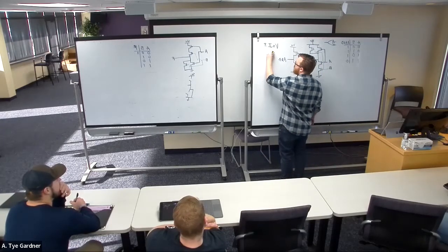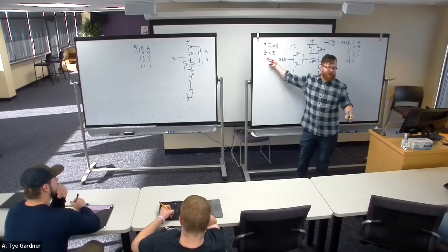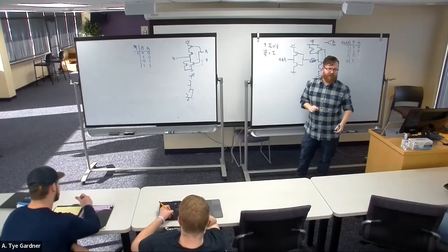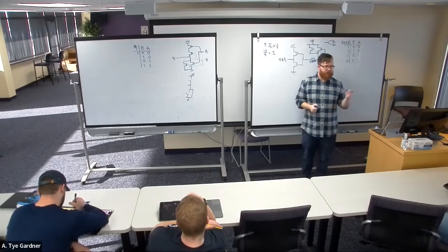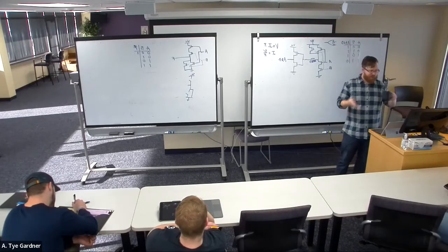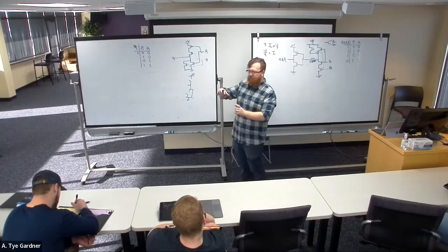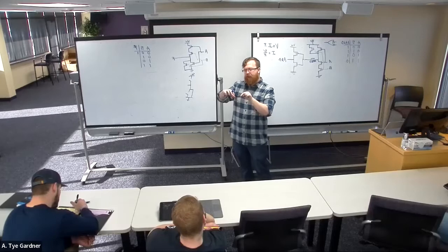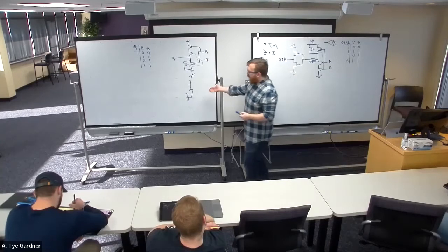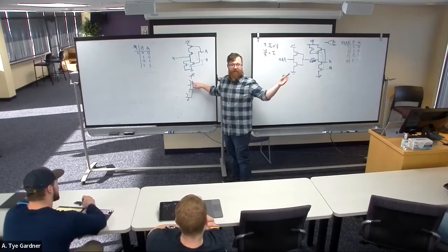We go from Ohm's law, we say I is equal to V by R. If R goes to 0, I goes to infinity, and I just broke everything, right? It burns up, starts fire, it smells really bad. Don't worry, it'll do that a couple of times throughout. You will start fires on your little breadboards. The breadboards that I loan out have little melty spots on them because this happens. But anyways, there's no path, right? So if I try and draw a line from ground, it follows here and it's broken. Everything's fine. This is a good circuit.